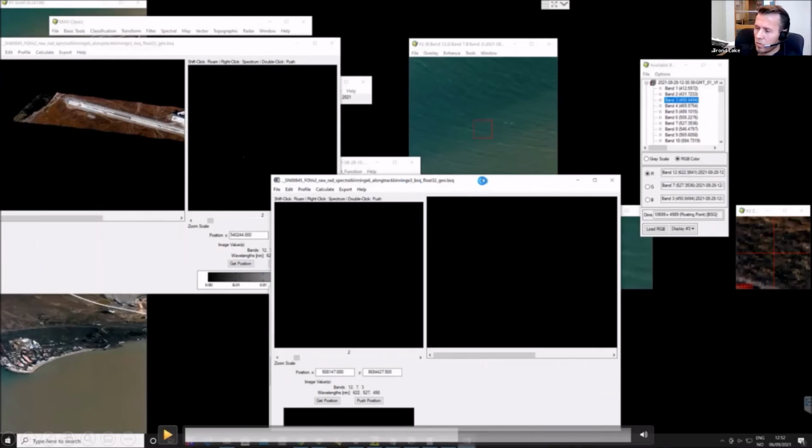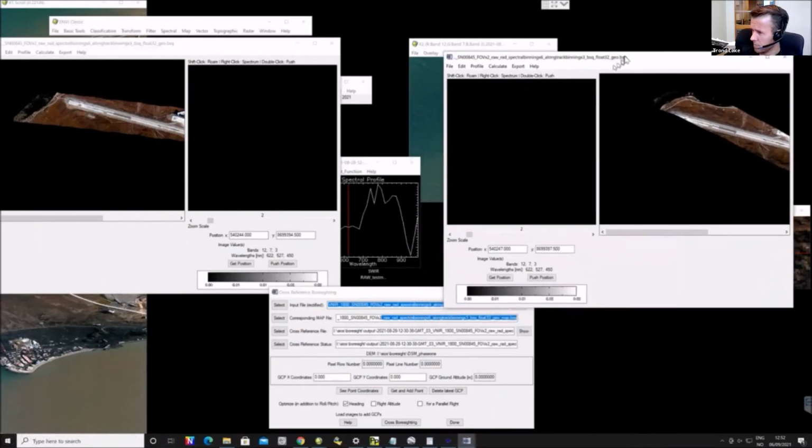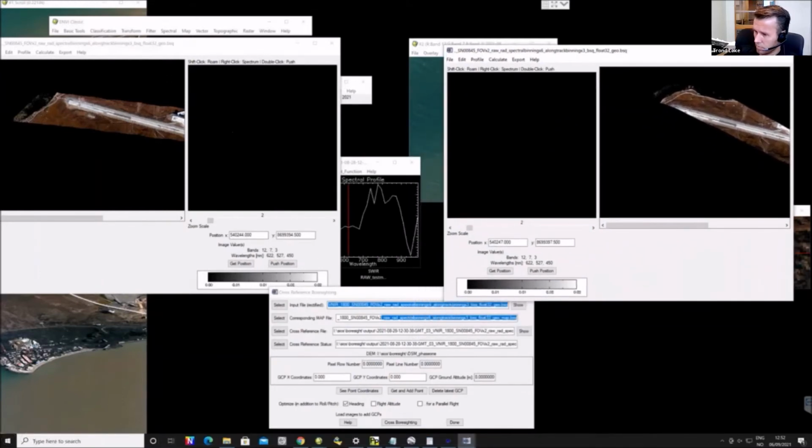So on this one, when I did the directory processor, I forgot to press guess range, because then it calculates a dimension that just fits the line. Here you can see there's a lot of dark pixel around, and all the dark pixels take up the bytes in the file. So these files could have been a lot smaller if I did that previously. Those are now the two flight lines.